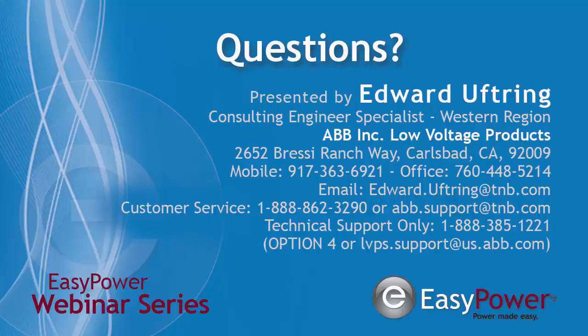So again, the electronic trip unit, there's some confusion. A trip unit is basically the unit that you put into the breaker to set those trip curves. The long time delay, the short time delay, the instantaneous time delay. An electronic trip unit, instead of just using dip switches, you are able to plug in with a computer, and you're able to set that so that it's more granular. So on the dip switches, you can do it in multiples of your rating. I believe it's 20%, 40%, 60%, and 80%. Since you're limited by the dip switches, you could do any combination of that.